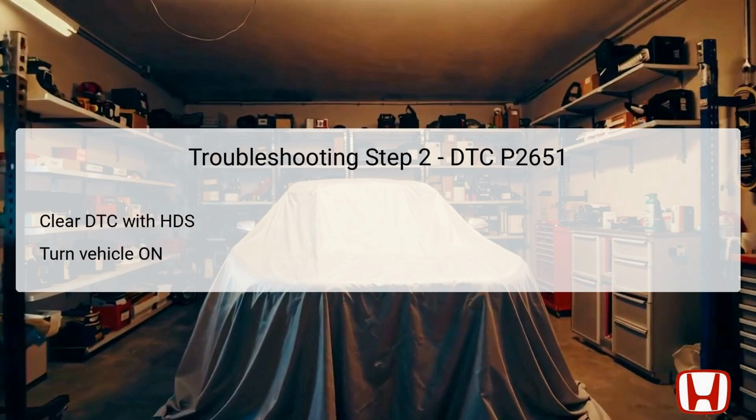In the second troubleshooting step, you'll begin by turning the vehicle to the on mode, preparing to interface with the Honda Diagnostic System, HDS. This system is essential for diagnosing various electronic issues within the vehicle. After powering the vehicle, use the HDS to clear the DTC. Clearing the code resets the system and can help pinpoint whether the issue is persistent or an intermittent failure.